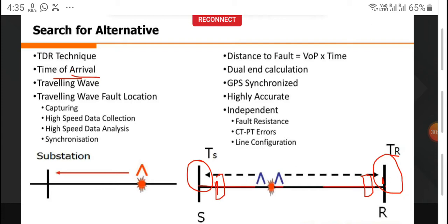Now, how do we know that exact length of the line? Because the measurement that is available with the people or the design system is that the length of the line is assumed from the gantry to the other terminal or the last tower, right? So to compensate for the sag, the traveling wave and the jumpers, what we do is adjust the VOP, the velocity of propagation of the waves that will be there when a fault occurs, by operating these circuit breakers, opening them at one end and then closing them. By doing that, we change this velocity of propagation.